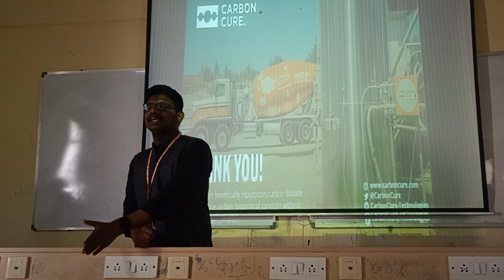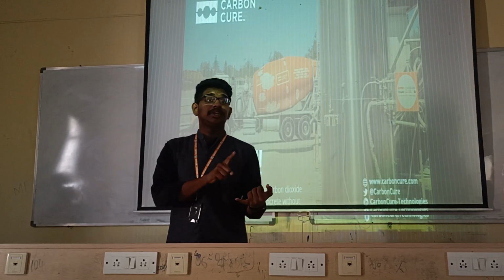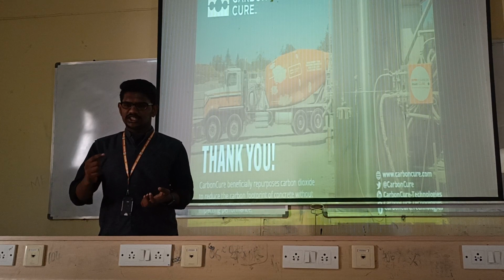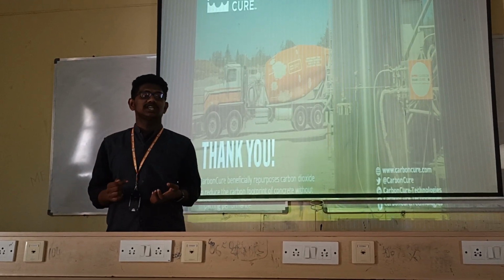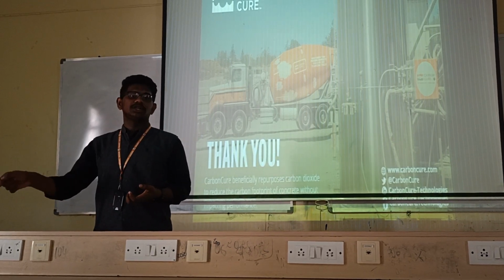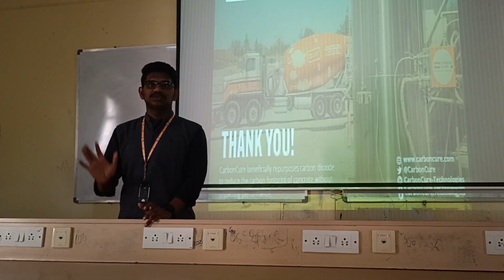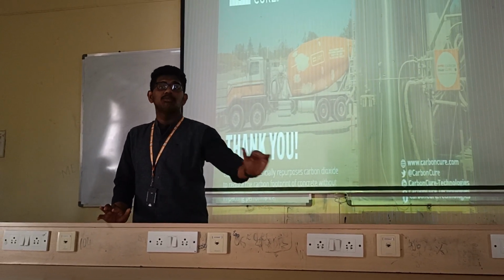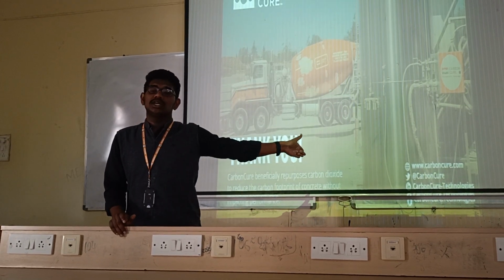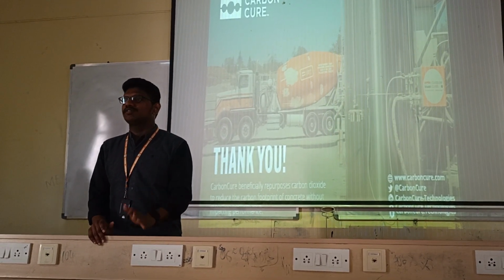These are all the effects that CCT has on the production of concrete. All the effects are positive. The compressive strength is increasing. The embodied carbon will be reduced. I need to mention this: after the injection of carbon dioxide is done, it is converted into calcium carbonate. So there is no carbon dioxide, that means there is no emission of carbon dioxide into the atmosphere. That means there won't be any embodied carbon if it is manufactured using CCT. That is very much better for our atmosphere.